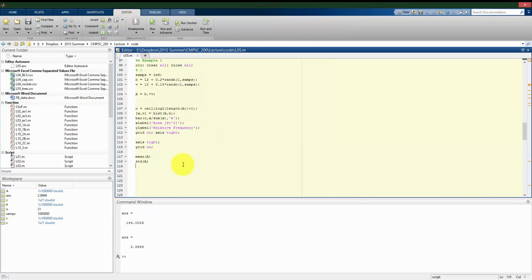So that's one thing we want to look for: if we keep rerunning the simulation, are we getting similar results? But to test whether we have used enough data points, we can look at convergence. And that's what we'll test in part 2. We want to see how many samples it takes until we have what's called convergence. There are a lot of different ways we can test for convergence. I'm going to base it on the mean of A. And we'll see how this works in a minute.